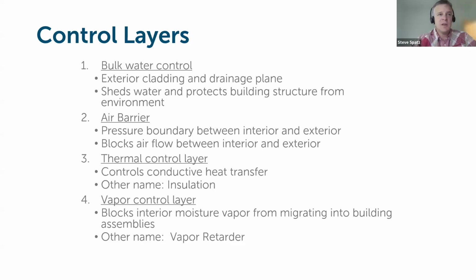There's been some recognition of the concept of trying to stop, and think that we can effectively fully stop, any moisture vapor from inside the building from getting into building assemblies, and putting in materials into those assemblies with that intention that it's going to be a barrier to entry, to shifting into a mindset of retarder, where we're retarding the flow of moisture vapor into these assemblies. Air tightness at the vapor control layer is critical as well, as it is with the air barrier, and yet giving an understanding and a pathway for drying potential to occur within those assemblies, either inboard or outboard or both, when and if moisture will load into assemblies.